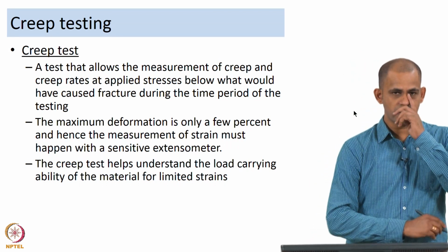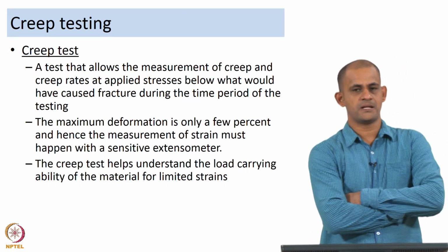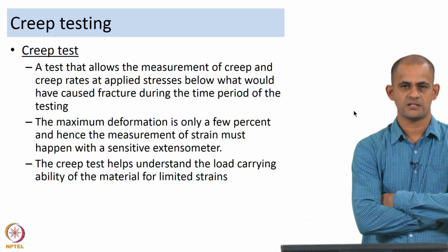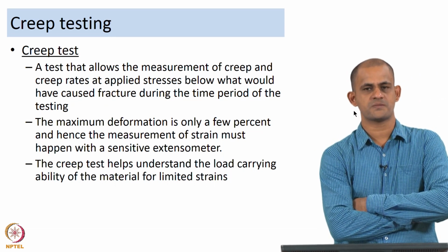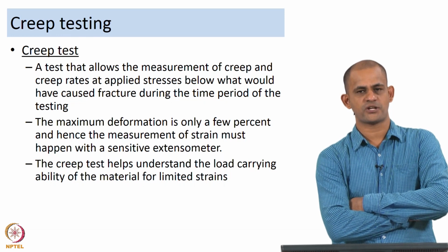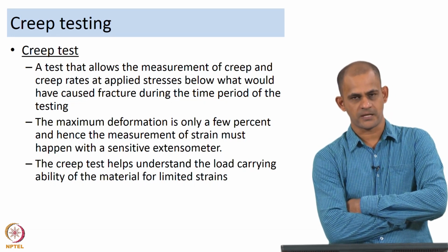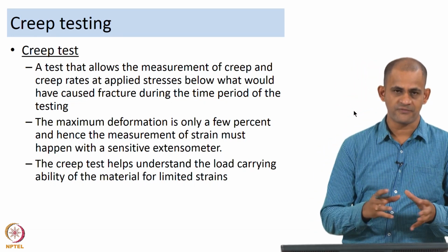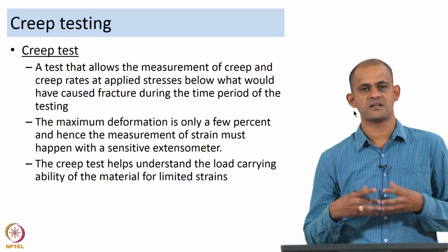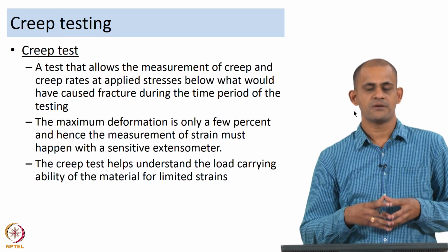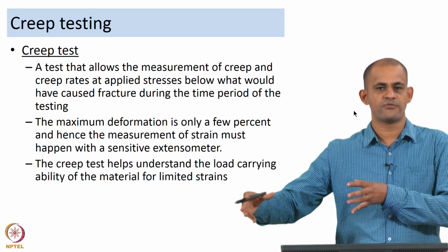So, coming to creep testing, a creep test is basically a test that allows the measurement of creep and creep rates at applied stresses below what would have caused fracture during the time period of the testing. So, this is the ASTM E139 definition, and what it tells is that the creep test is a test where you are not taking your sample to fracture.